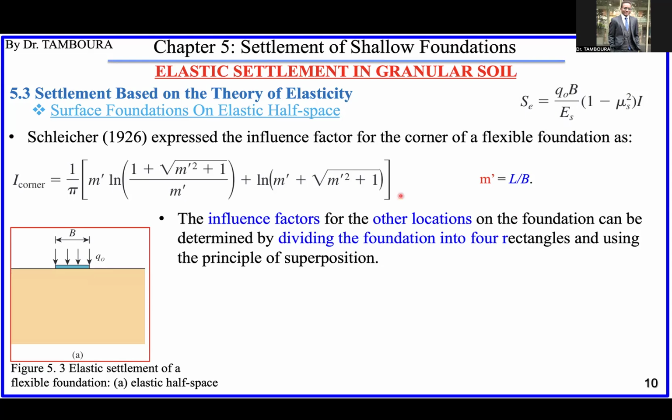So for the other location, if you want the settlement at any other location under your rectangular foundation, you can divide the foundation into 4 rectangles and use the principle of superposition.